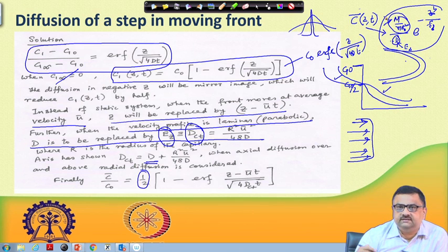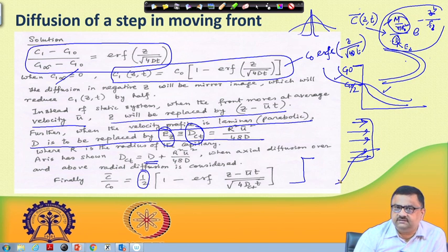One is to just put a pulse, and see what would be the stretch or spreading of that pulse. Otherwise you put a step change and continue. I have given a step change here, and after the residence time I see the step change is showing like this. How much is the spreading, how much is the front smeared? This is something we can see.